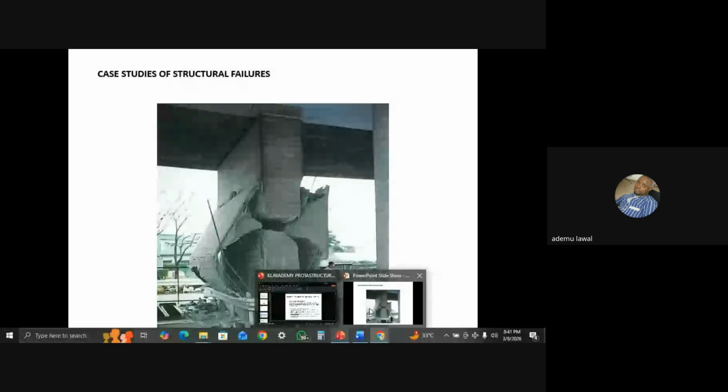You redesign that particular buckled pier, I think it will provide good safety, and it will be economical by making sure that the load carrying capacity of the new pier is increased, or you do it from two supportive sides, closer piers with the buckling at the middle, until the two are constructed and raised with the help of a bearing that the upper part will rest on. Thank you. Thank you very much.